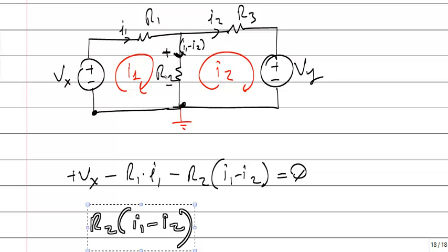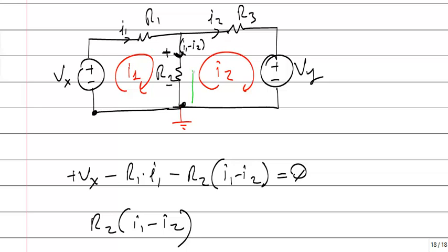That current flows downwards, so the upper side is positive, the lower side is negative. If I am drawing a KVL loop like that, I am switching from minus to plus. It means there is a voltage increase. This side is high, this is low. So voltage is increasing. I have to say plus.